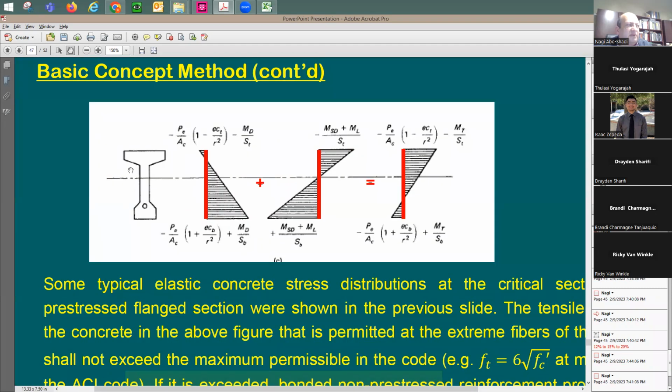During the service life of this bridge girder, how much stress would you like to see here? Because this now is going to become what? Look at this. This is going to be from pre-stressing, so this is going to be the positive side, right? I'm going to have here some tension, if you really would like to have a beam free from cracks, right?